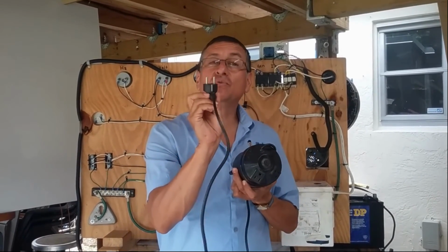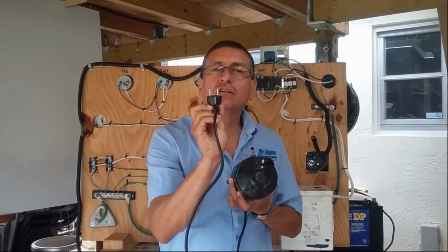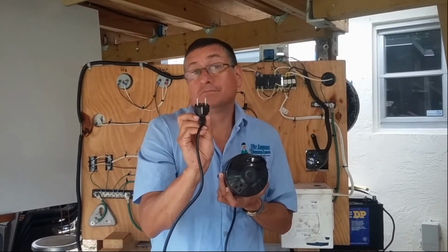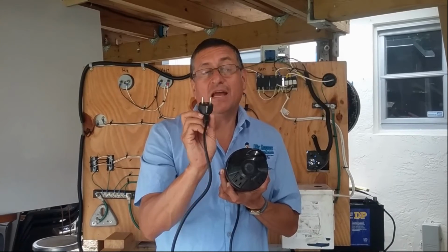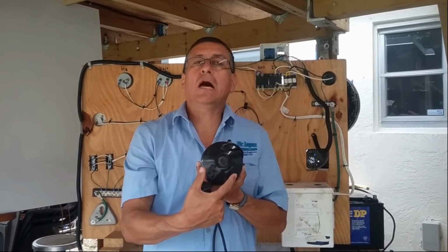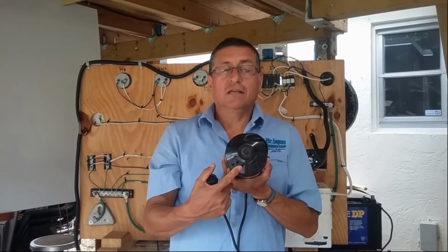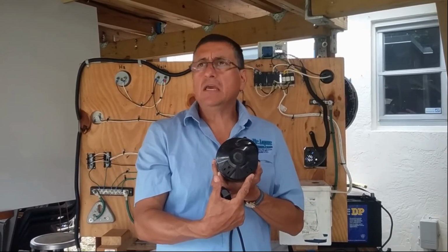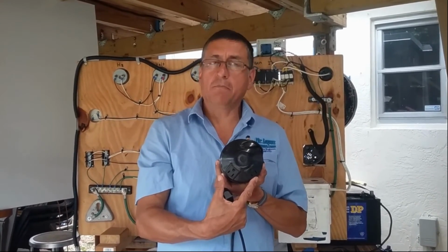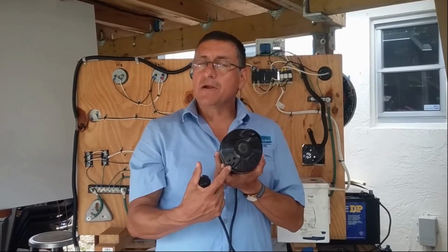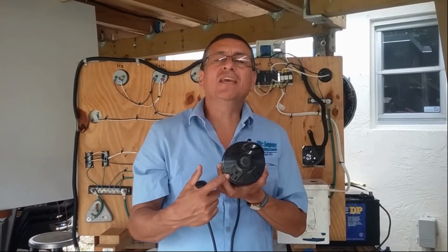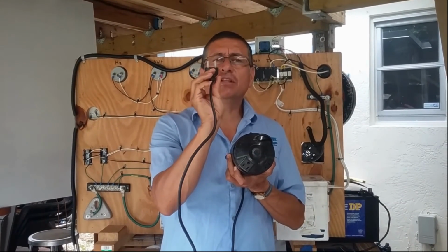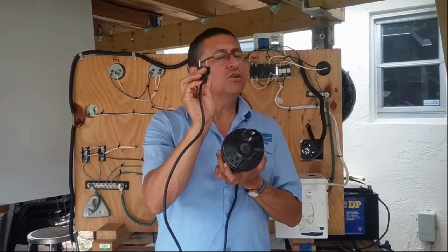You see, you reduce only the voltage with the step-down transformer. The frequency is the same. What is the inconvenience with those outlets? Those outlets right now are 115 and 115. Okay, it's pretty close to 120, the American power. But remember, the frequency here is 50 hertz because you reduce the voltage. The transformer is used to reduce the voltage, not the frequency.